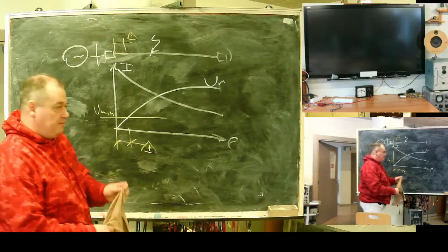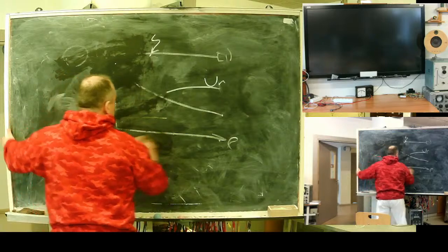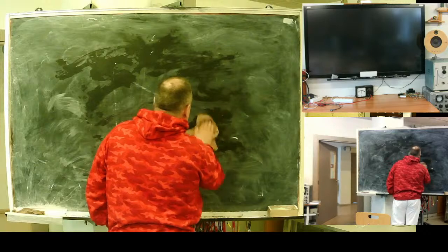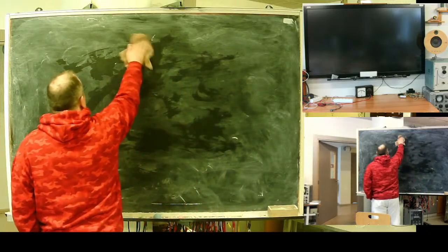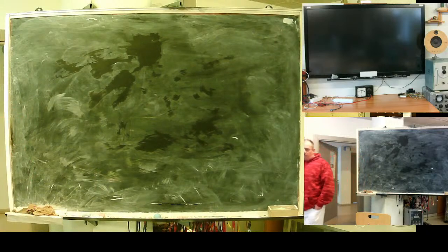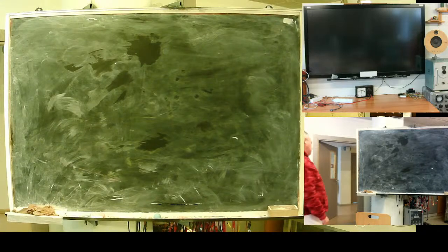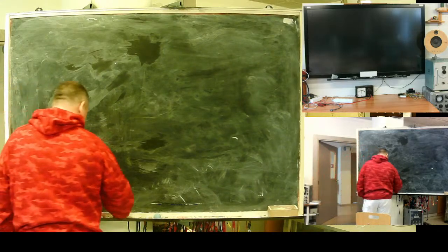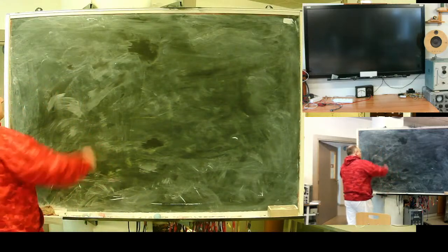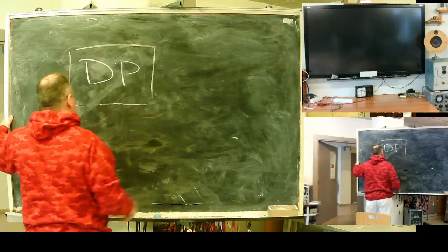Where to run? It is mandatory to back up your distance protection with non-selective overcurrent protection. It's mandatory. So you have distance protection module.